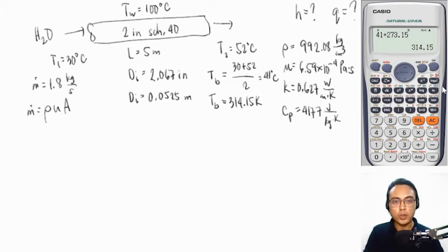Notice that I used all of the standard units in the SI system so that we will not have any problems when computing the dimensionless numbers later. Okay, these four physical properties, density, viscosity, thermal conductivity, and heat capacity, will almost always be used in your calculations in convective heat transfer. So please practice obtaining these values from your handbook.